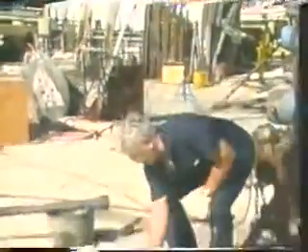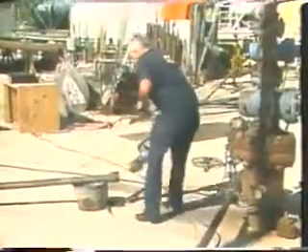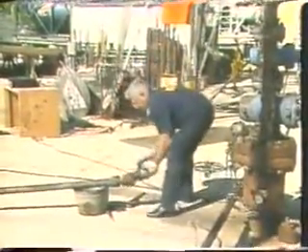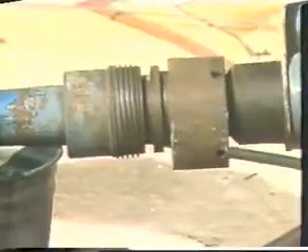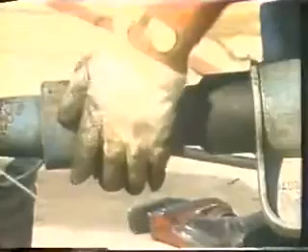The wireline is threaded through the stuffing box and attached to the wireline socket by tying a knot in the wireline. The wireline socket is screwed onto the tool string, and the completed tool string is pushed completely into the lubricator. Now the stuffing box can be attached to the top of the lubricator sections to complete the lubricator assembly. The stuffing box seals off around the wireline to contain the well pressure in the lubricator stack.